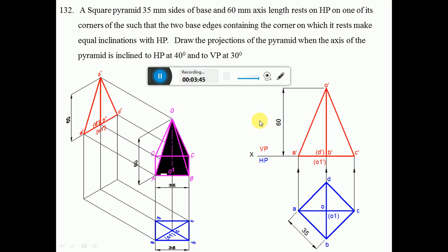Now we have to draw the sketch. First consider any point, then using the protractor, measure 45 degrees with respect to the vertical on this side and 45 degrees on the other side, and draw these two lines. Using the compass, measure a radius of 35 mm and with A as center cut an arc on this line to get point B. Similarly, cut an arc on the other side to get point D.